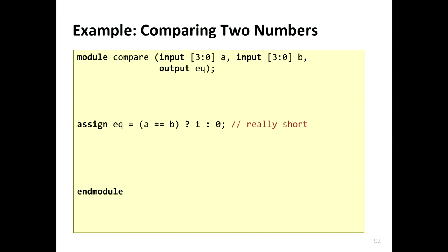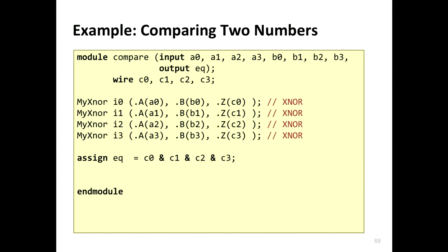You can have 4 input ANDs as well. There are predefined libraries which you can use, so you can also use 4 input ANDs. The one that I showed you is actually going to be a 4 input AND, but it depends on what libraries you tell the synthesizer to use.